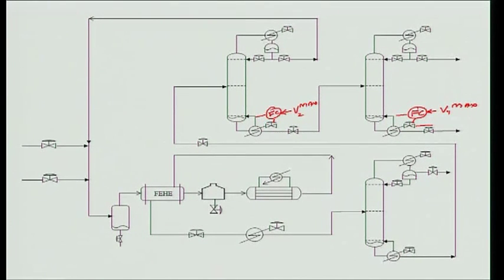Then what was the other constraint that was active? Yeah, the other constraint active was P reactor max. So this is going to be pressure. This is the same as before. Here I get this because I want to operate the reactor at maximum pressure. Also I have this loop because composition control of C12 is by adjusting reflux, and this will be a nice and tight loop. So these loops I have put in place just based on constraints at maximum throughput.